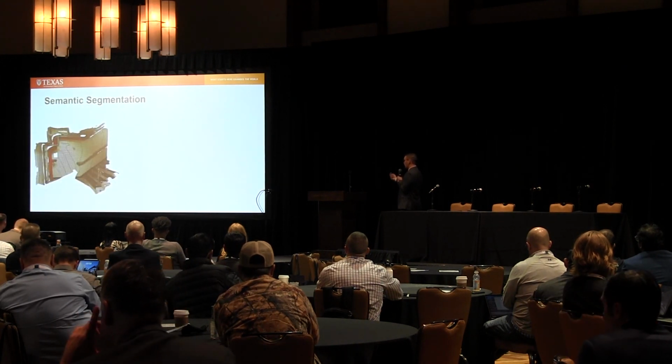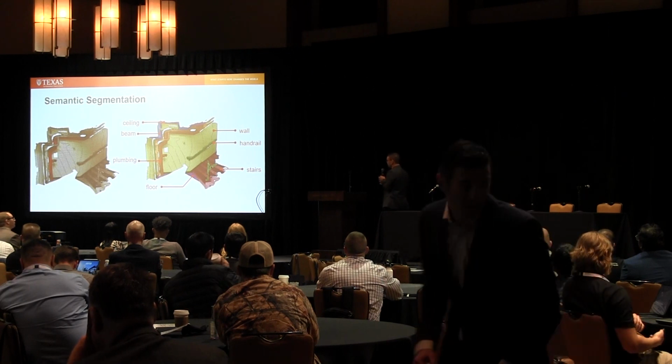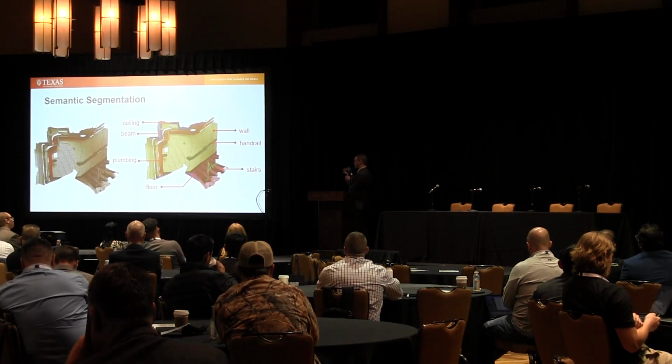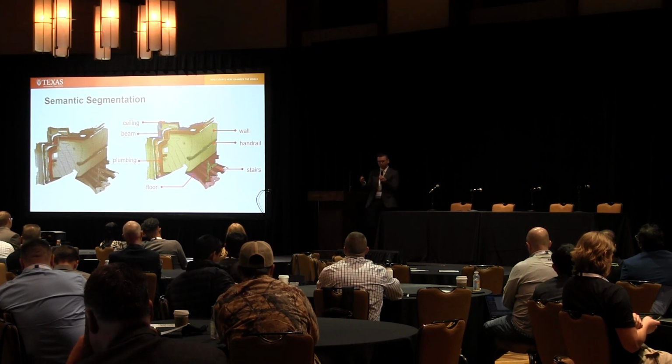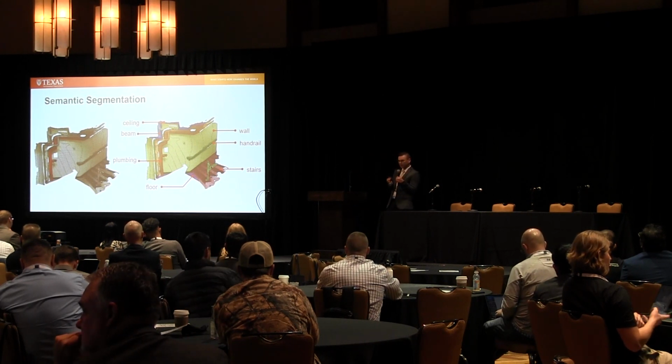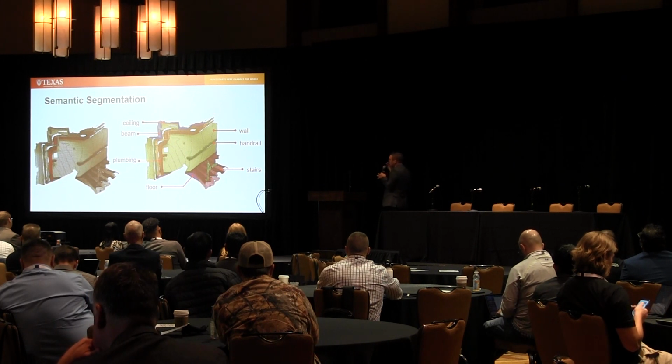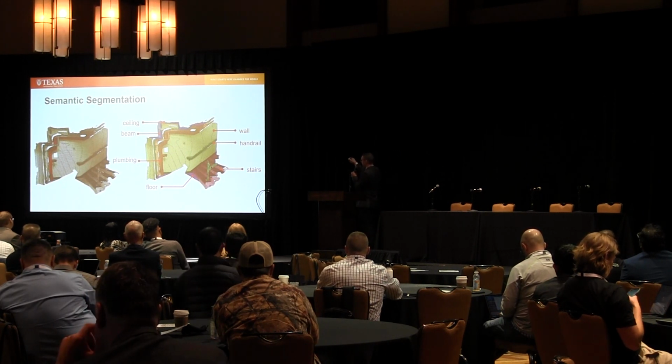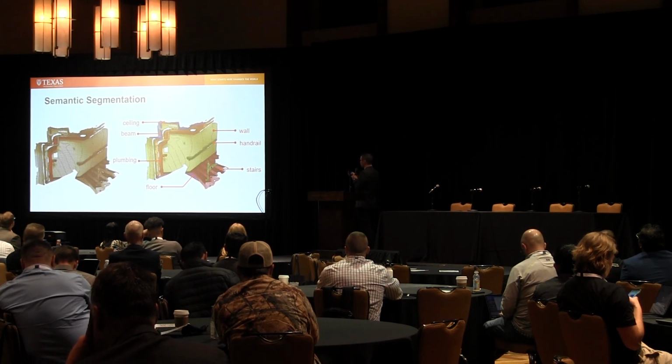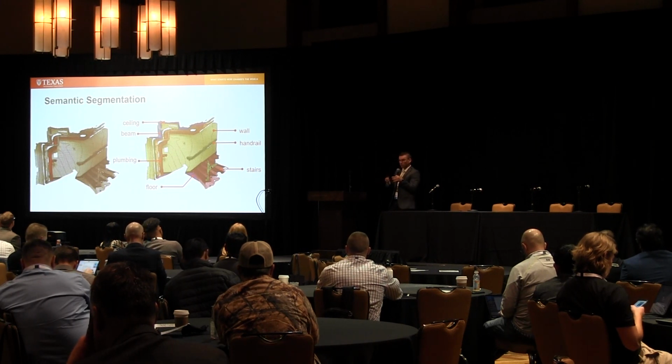And so what their work aimed to do is develop algorithms that could automatically start to understand and parse that scene. A big part of the scan to BIM workflow involves something called semantic segmentation. Basically, how you can intelligently understand and segment and cluster that scene into objects, whether that be ceilings, beams, floors, walls, doors, etc. That seems to be the biggest first hurdle when developing an automated scan to BIM process: just how do you tell an algorithm what objects it's looking at.